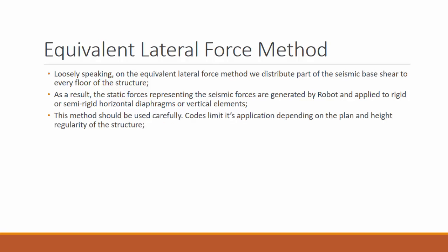This is the simplest method to define seismic loads, but you should be aware the codes, the American and European ones, limit its application depending on the plan and height regularity of the structure.